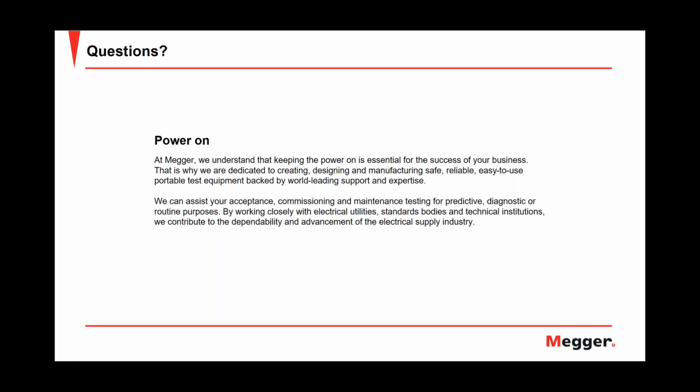And ARM stands for arc reflection method, because the TDR, like Javier was explaining, on a pinhole fault cannot find the pinhole fault, because we need maybe a flashover voltage of a couple kV, and the TDR signal is only a couple volts, maybe 50 volts. So we have to help the TDR by providing a short circuit at the fault, and we provide that short circuit by putting a high voltage on, which creates a flashover.